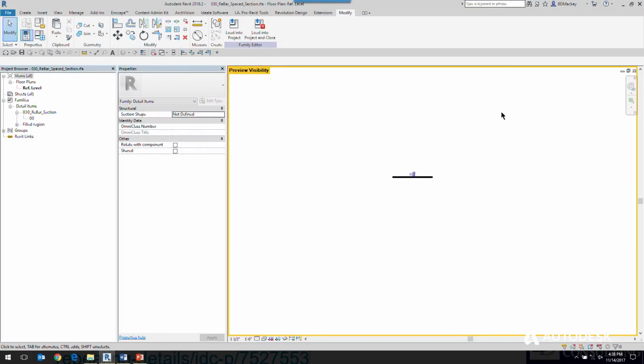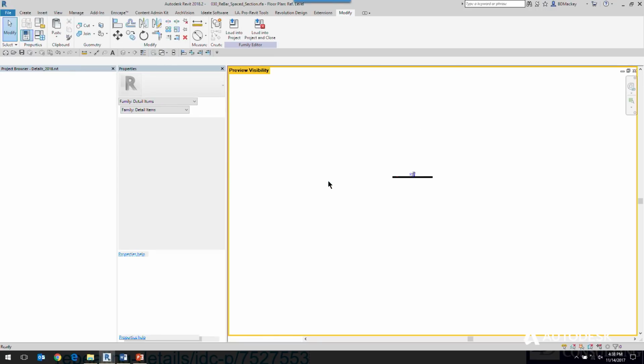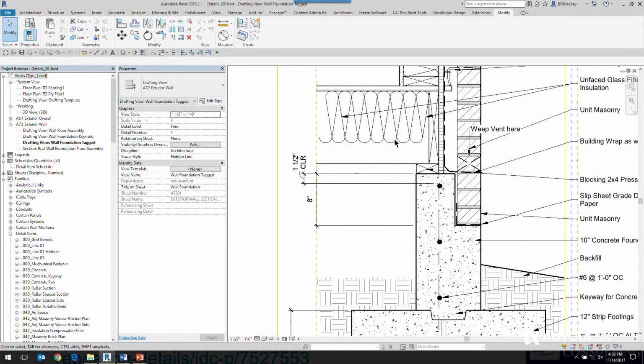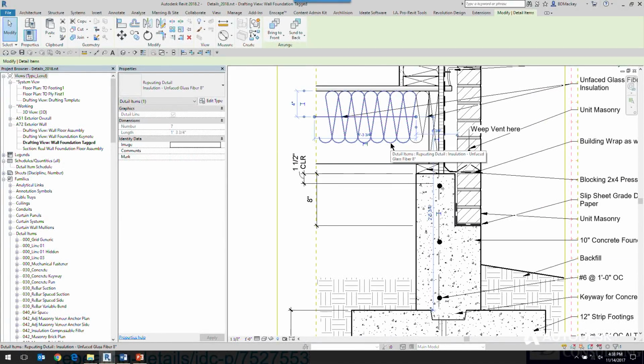And then the last thing that I like to also show here is kind of one of my little tips behind the scenes. Let me get back to the project environment. So the last little thing I have on here is there's some tools in Revit like the insulation tool. Somebody uses architects, I guess, and the architects use the insulation tool out of Revit. It's really, really cool. But it's a repeating detail. You can't tag it. You can't keynote it. So personally, I rarely use the repeating detail component. I did here to show an example of this.